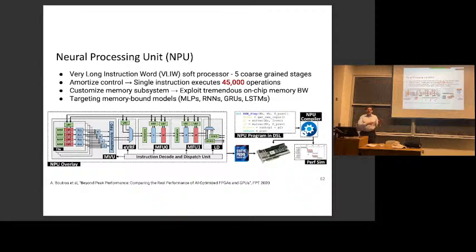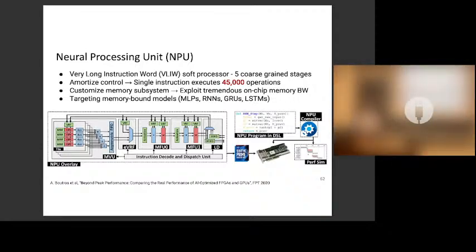So what comes out of this matrix vector unit just flows through the other units. And that's again to minimize data movement. Data movement costs a lot of hardware and costs a lot of energy. So if you can directly send it to the next unit instead of looking it up from a register file, you can be a lot more efficient. Okay, and I already talked about this. It's not targeting all neural networks. So it's not targeting CNNs, for example. It's customized to a certain sequence.